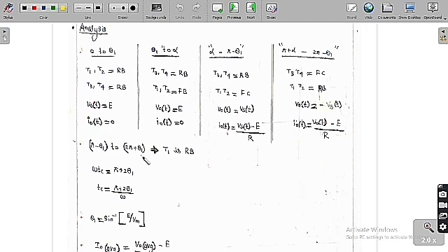So simply we can say that from pi minus theta 1 to 2 pi plus theta 1, T1 is reverse biased. Therefore a reverse voltage is going to appear across T1 from pi minus theta 1 to 2 pi plus theta 1. So omega Tc is equal to the difference of these two, 2 pi plus theta 1 minus (pi minus theta 1), and we are going to get pi plus 2 theta 1. So (pi plus 2 theta 1) by omega is called the circuit turn-off time of the main thyristor.